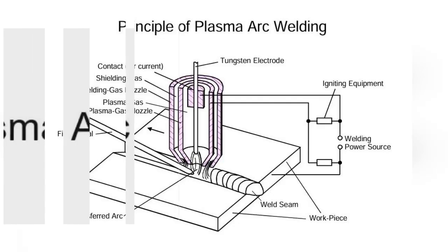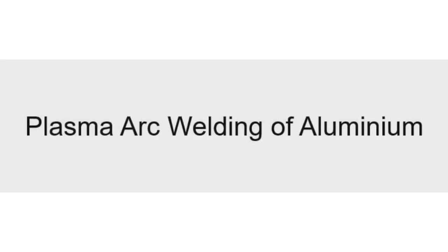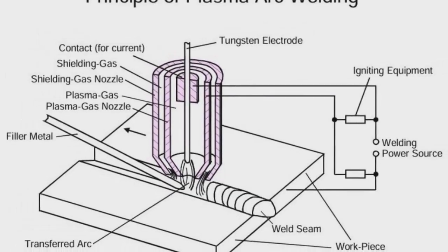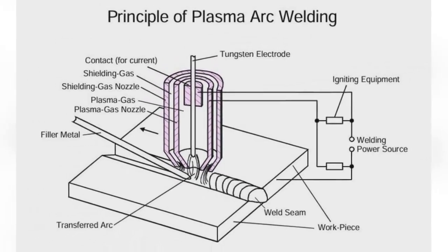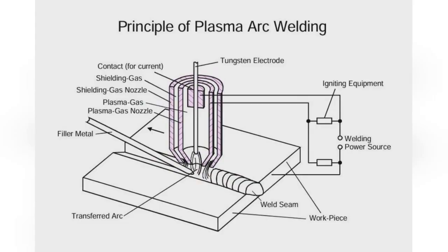Thermal plasma consists of electrons, ions, and neutral particles existing in a high-temperature environment. These elements undergo chaotic movements, causing molecules to dissociate and atoms to ionize. The plasma is concentrated in the inside of the jet, thereby delivering a narrow plasma jet with a very high energy density. The plasma arc is, therefore, constricted and arcs between the tungsten electrode and the workpiece.